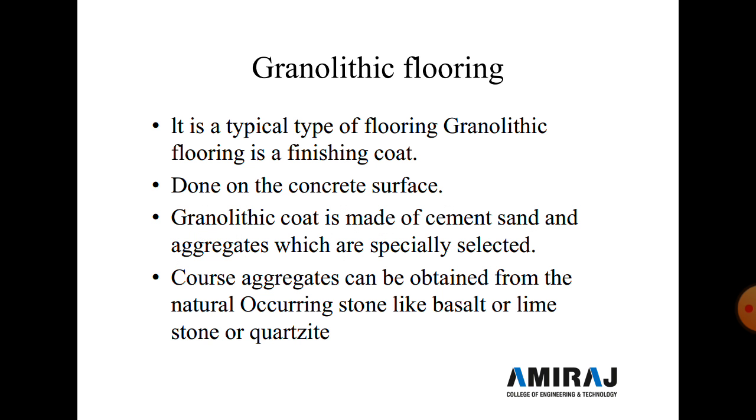Now the next type of flooring is granolithic flooring. It is a typical type of flooring. Granolithic flooring is a finished coat done on the concrete surface so as to obtain a hard, durable and abrasion resistant flooring, and the granolithic coat is made of cement, sand and aggregate which are specially selected. Note that the grading of the aggregate plays a very important role in such a type of floor.